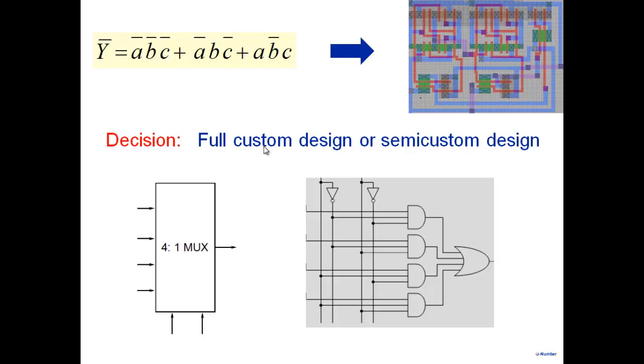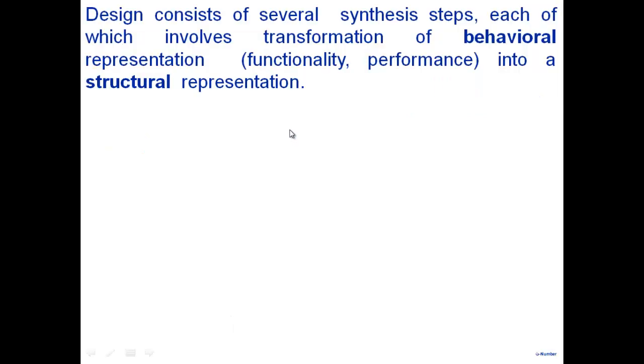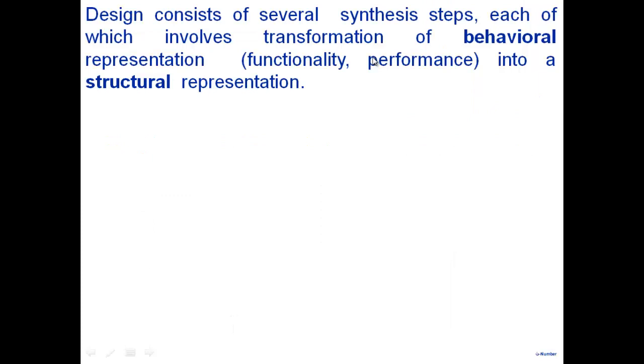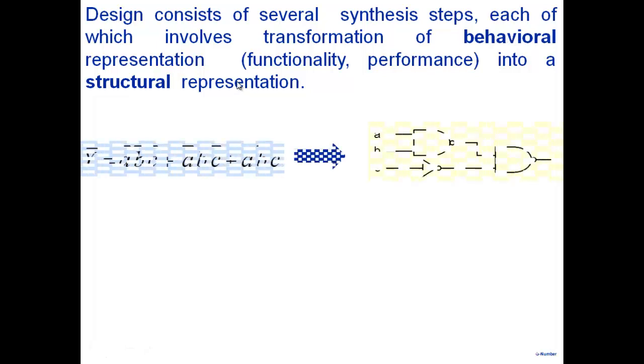But what we are interested in, let's say we want to design the minimal area with the best delay, all that, we want to do a full custom design, okay? So our design will consist of a series of steps. We can't jump from a logical expression to a layout in one step, okay? So we'll have a series of steps here. And in each step, in general, a series of synthesis steps, what you're doing is you're transforming a behavioral representation into a structural representation.